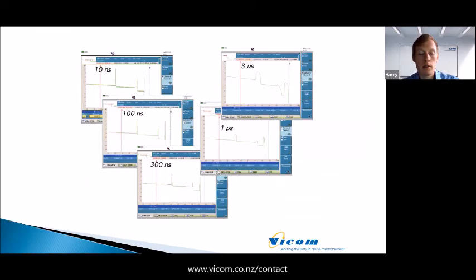So here we can see the differences in pulse width and the importance of selecting the most appropriate one for your application. This is the exact same trace run multiple times with varying pulse widths. We can see a 10 nanosecond pulse, how high resolution it is. We can see how clear and accurate each of the event locations are. As the pulse width increases and grows, we can see that these events are getting wider and wider and they're not as precise. So the resolution that we're getting on the trace is falling away as we increase the pulse width. We can see here that on a 10 nanosecond pulse, the event dead zone is almost negligible, it's very, very small indeed.